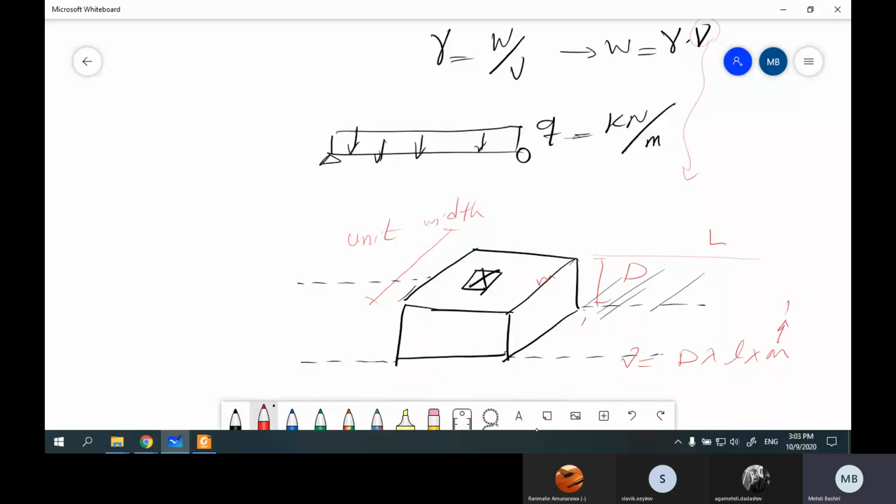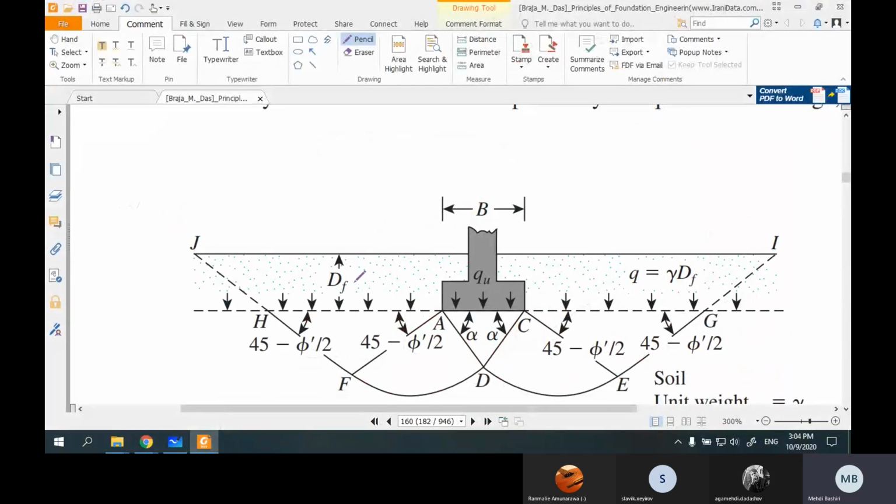of the foundation. And when you want to find the capacity, the final capacity, you say that this foundation, for example, has Q of 10 tons per meter. L you are not considering, or you can also assume it as unit or one. All I want to say is that when you want to find Q, you just need to consider D, or in foundation we say DF. So the first parameter that you should know in your calculation is this parameter DF.